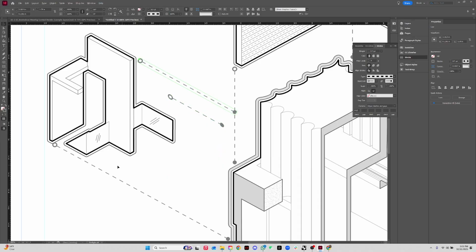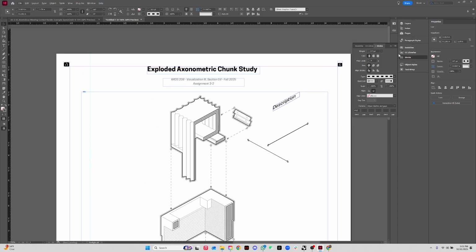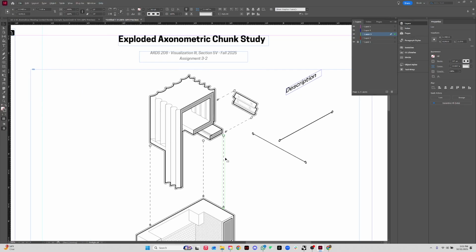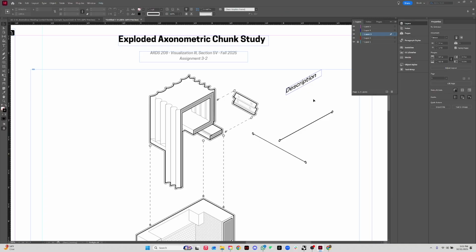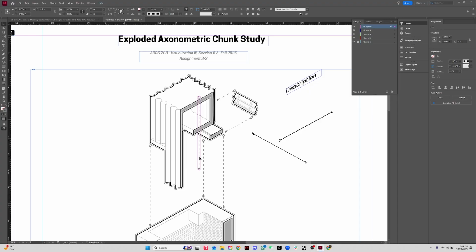And one more tip in terms of changing layers. Let's say that you have one line in a layer, but you want to change it. Like, let's say that I want to change this layer to the pink layer. The best way to do it is that you Control C, you copy it, then you delete it, and then you go to the layer, the pink one, and then you Control V, you paste it, and then it comes into that layer. So that's a nice way, if there's something that you want that's from another layer, you want to transfer it, you can do it this way. Well, before you delete it, you Control C, obviously make a copy of it before you do anything, and then you Control V and then you get it on the layer.